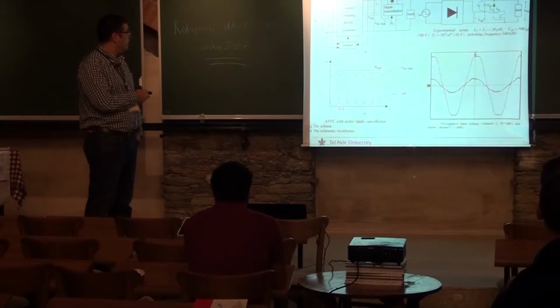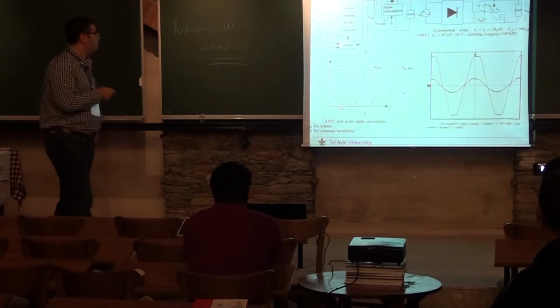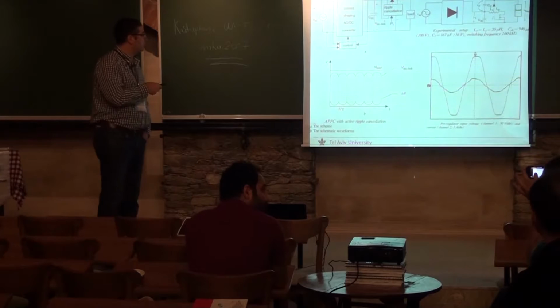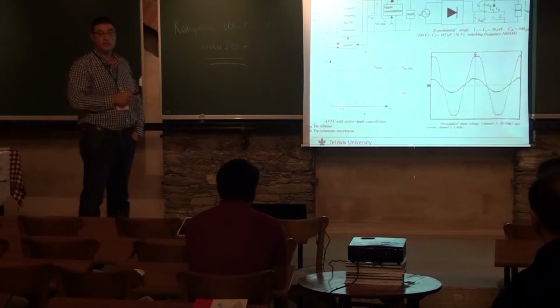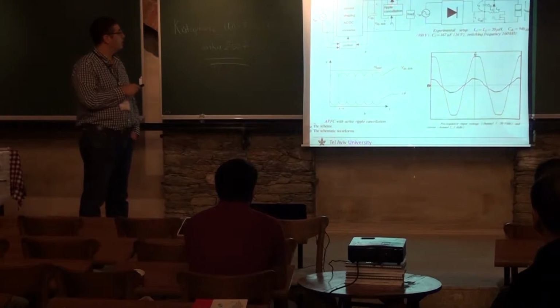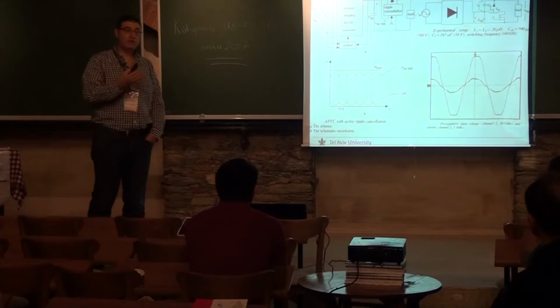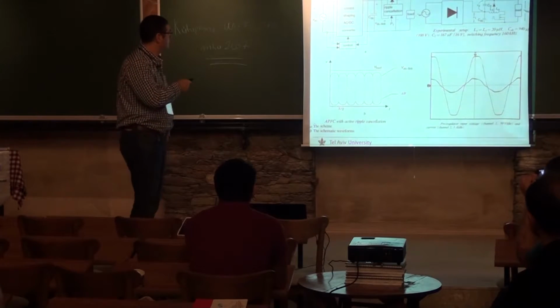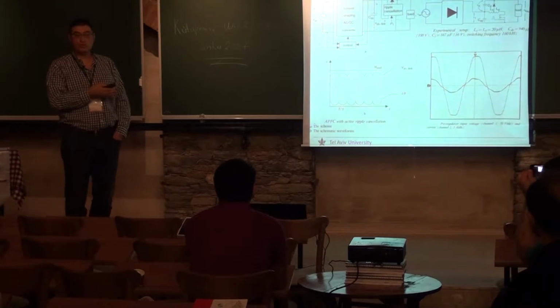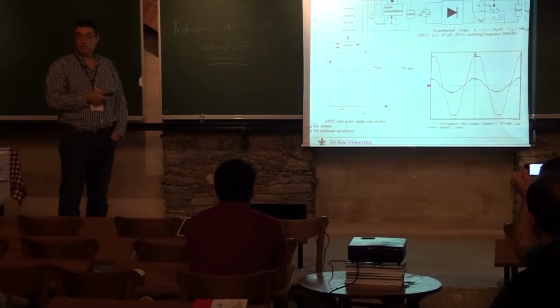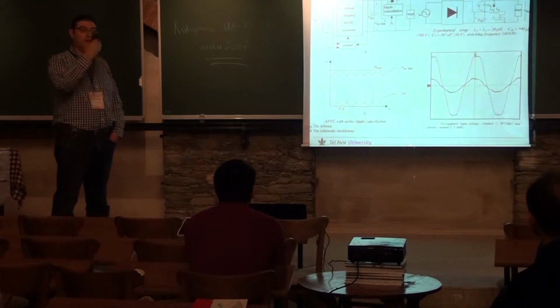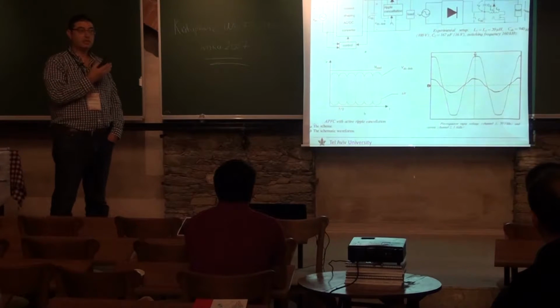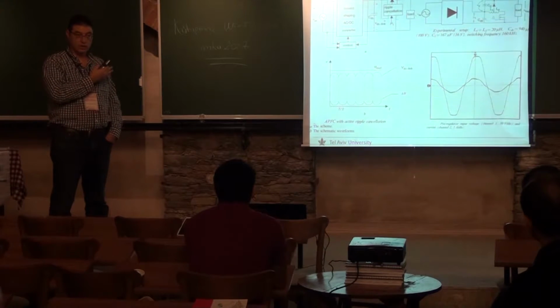So what's the idea? That's the rectifier system. And then we have the DC bulk, DC link capacitor, across which typically there is 350 volts or so, because this stage is typically a boost converter, and therefore the DC link capacitor has to withstand a little bit more than the maximum amplitude of the AC, right?